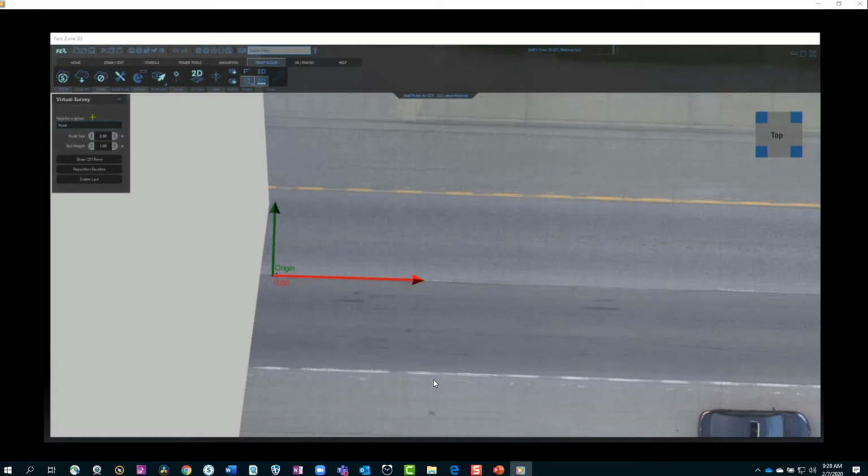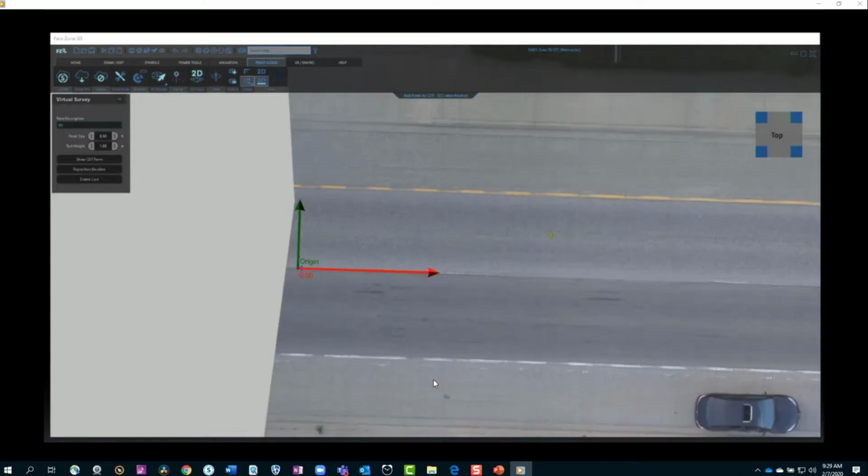Now, here's a properties box, like a lot of the FARO Zone features. It comes up to allow you to work with and adjust various items. The box here for new description is where you'll be adding the code or description of the piece of physical evidence that you're collecting. Okay, I'm going to start picking some physical features in our diagram so we can plot them using the virtual surveyor and get them entered into the coordinate data table.